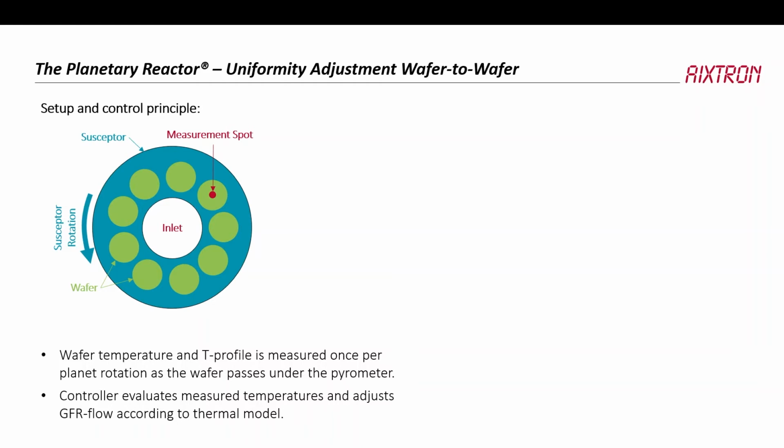Not so easy for the silicon carbide, but for the gallium nitride based applications, we can use a 400 nanometer pyrometer, which is quite tricky to do, because if you look at the black body radiation curve, and look at 400 nanometers at these temperatures, you are essentially counting individual photons coming from the surface. But with the right equipment, it can be done. So you can actually measure the surface. You're not looking through the wafer, but you can measure the surface temperature of the wafer using such equipment.